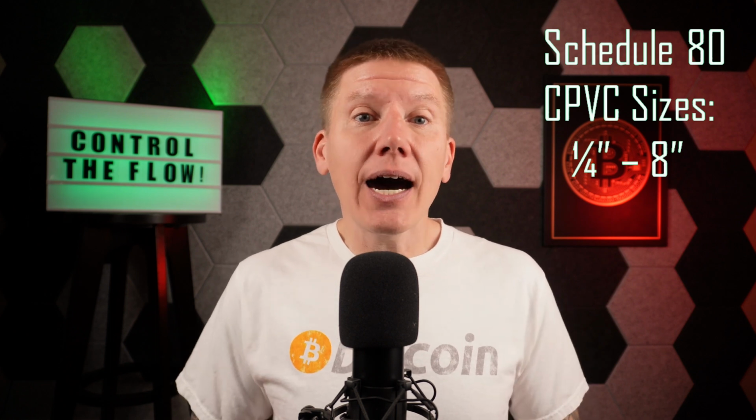The other type of CPVC piping is Schedule 80 pipe, which is gray in color. It is much thicker and heavier built than Schedule 40 pipe, and it is available in sizes all the way up to 8 inches in diameter. It is much more expensive than Schedule 40 pipe, and you're going to have to go to an industrial supply shop to buy it. And the final type of piping is flexible tubing and hosing.